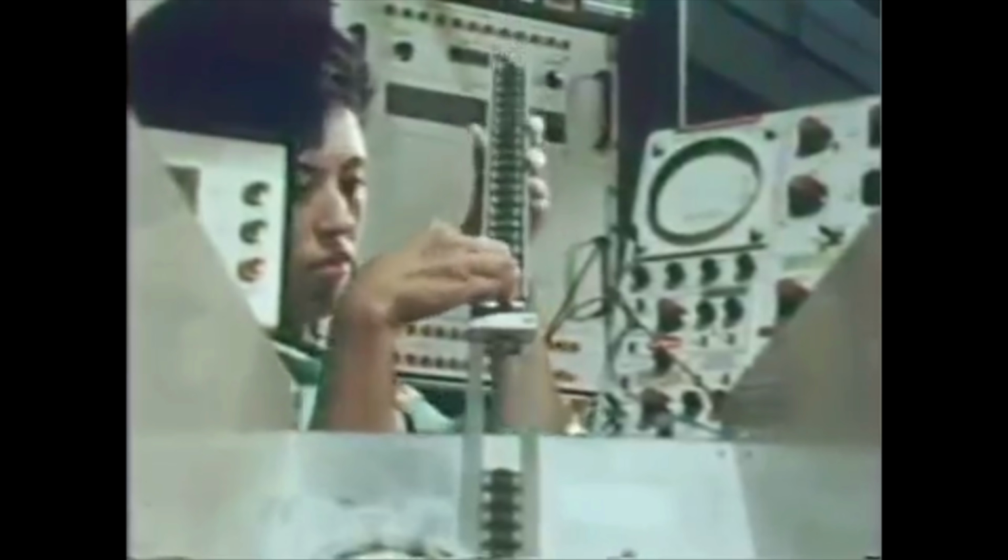Now that the circuit has been packaged, we must again test it substantially before we would dare ship it to the user. First is a series of electrical tests, many of which use special test equipment, which is again built from integrated circuits. Many of the tests made on the integrated circuits now duplicate those tests which were made on the wafers. In addition to these tests, which duplicate those which were made before, we must make some special tests, such as frequency response of a linear amplifier or switching speed of a digital circuit, before we would dare ship the unit.